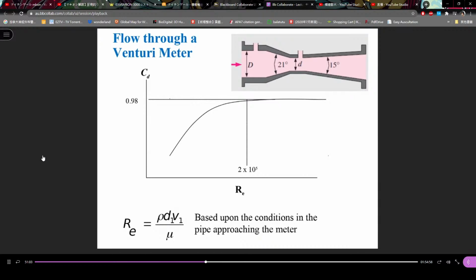And for different Reynolds numbers, higher means higher velocity, more turbulent, and better. Why is the discharge coefficient close to 1, close to 0.98? So if we use this instrument to measure velocity, flow rate, the Reynolds number should be higher. Understand me? Otherwise, the accuracy is not good. So for different kinds of Venturi meter, check the requirement of Reynolds number for measurement.